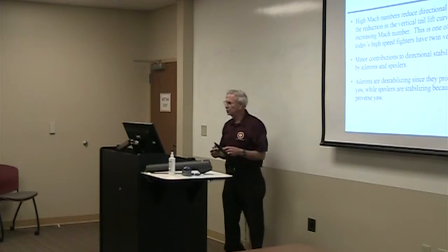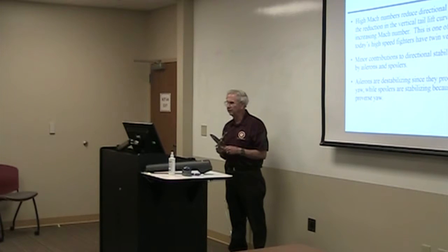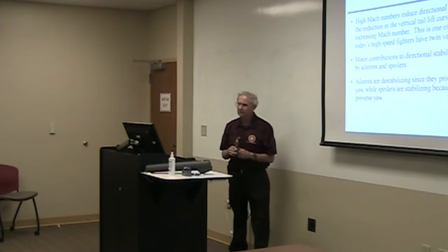High Mach numbers reduce directional stability due to the reduction in the vertical tail lift curve slope with increasing Mach number.